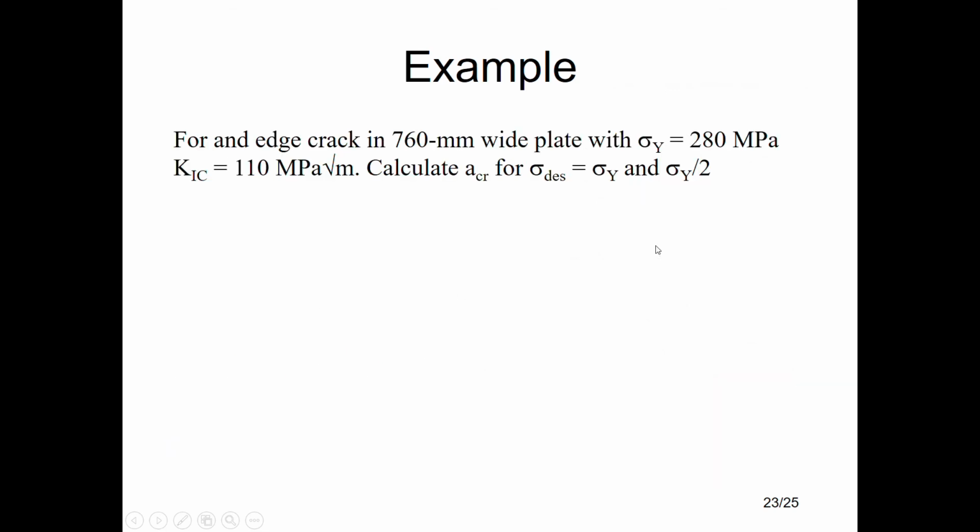Okay, for another question, for an edge crack in a 760 millimeter wide plate with sigma yield 280 megapascal, this is another question, which I believe you can do by yourself. Try to find the critical crack length for this type of design stress. Okay, and this one.